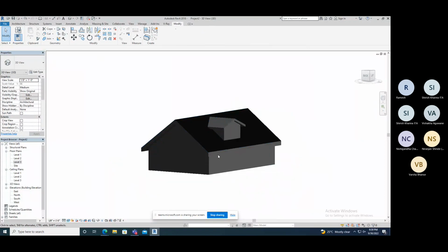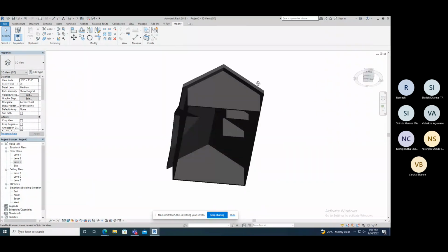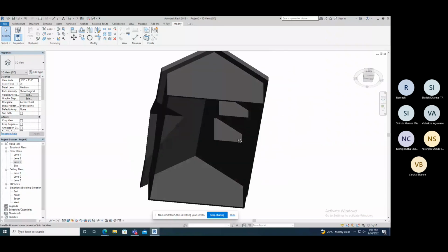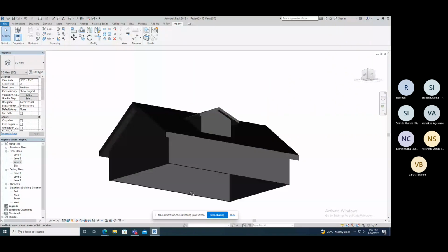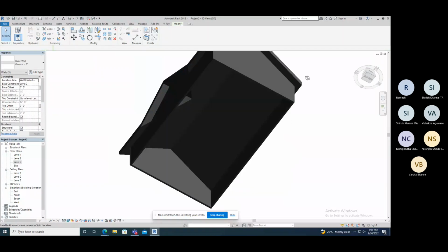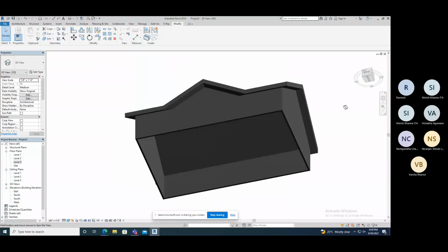But you can see one problem is there, that three walls are additional here in the bottom. Now we need to attach with the bottom roof. Yes. Again, select all three walls and attach with. This time you need to use base, and the base is attached with the bottom roof. See, it is okay. The walls are not there.